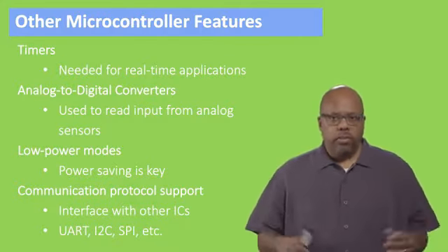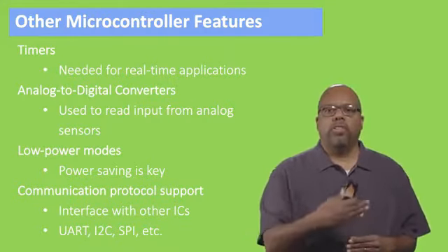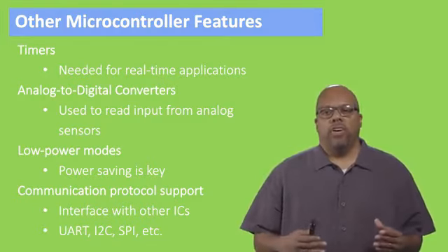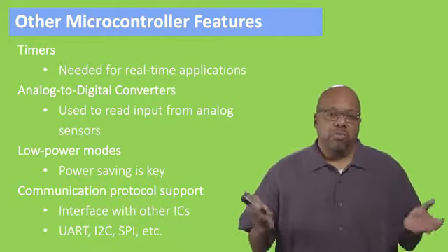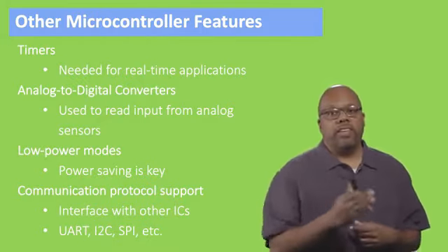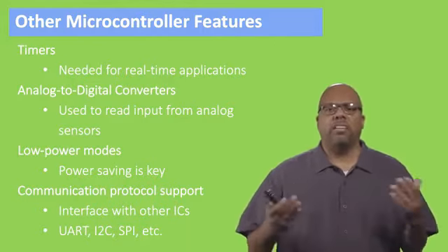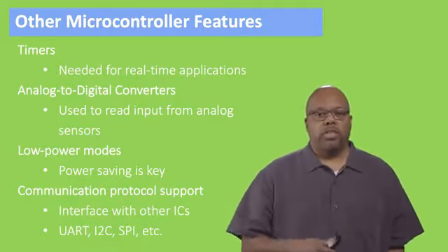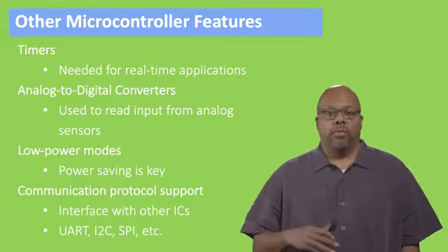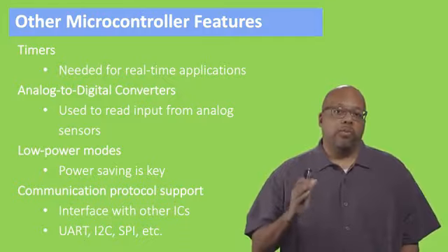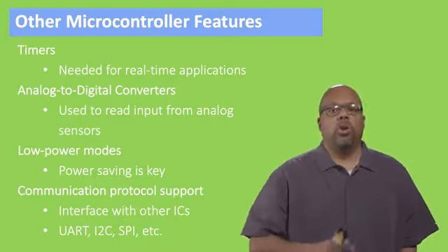Communication protocol support. We'll get to this more later, but these microcontrollers have to communicate with other integrated circuits, okay? And the way that they communicate, they use some kind of a relatively simple communication protocol. The way that they send data to and from each other over a set of pins has to be in a certain order with a certain timing and so on. That's the protocol. And we'll get into more detail about these protocols later, but some of them are UART, I2C, SPI. Those we'll cover later in the class, but these are protocols that you can look for in a data sheet and say, yes, it supports I2C, yes, it supports SPI, yes, it supports UART, right?